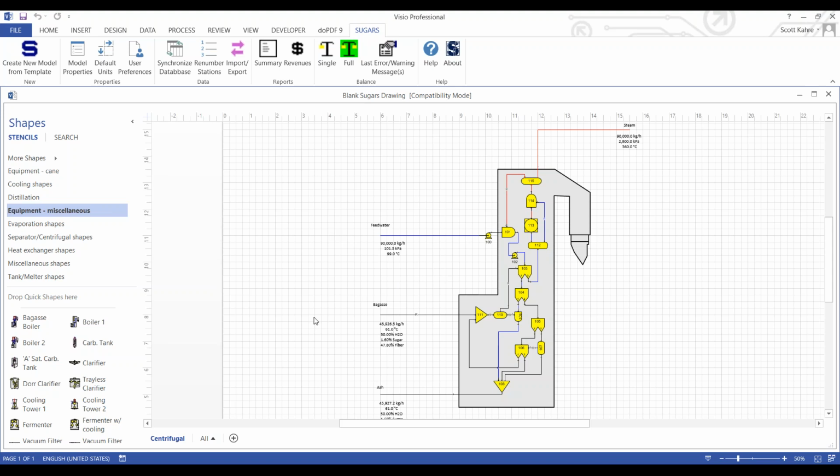So let's take a look at what happened. We have 90,000 kilograms per hour feed water coming to the boiler. We specified that in the external flow stream dialog. It was at 1 atmosphere, 99 degrees C. And the steam that's being produced is the same amount because we did not separate any water from the stream, the feed water within the boiler station grouping.